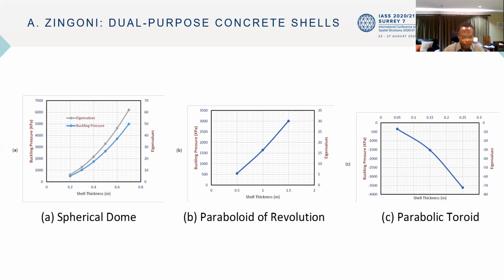A nonlinear buckling analysis taking into account geometric imperfections has just been completed, but the results are not included in this paper. This study has shown that the likely size of imperfections will reduce the linear buckling pressures by only 20 to 60%. Thus, the shells would still have good margin of safety even after taking into account the possibility